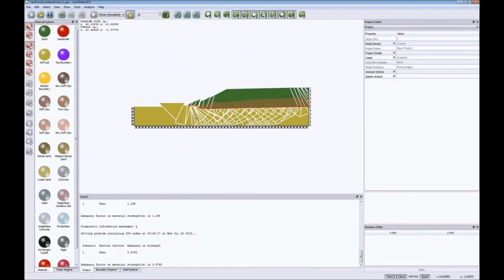So effectively it's like a kind of vertical compression almost, and just extrusion of this soil out sideways. And that's going to be quite difficult to model correctly using say a slip circle type method, which will overestimate the capacity. I should say that this symbol down here denotes a symmetry boundary condition, so we're actually modeling half the embankment in this particular case.